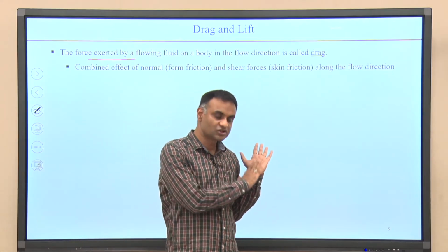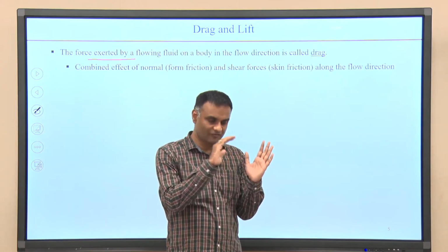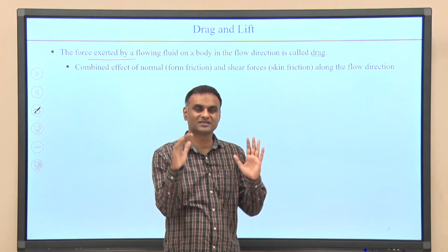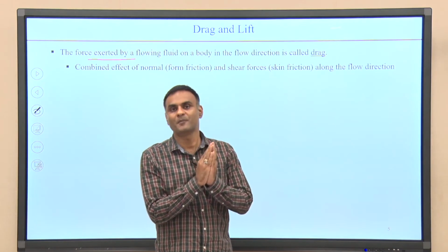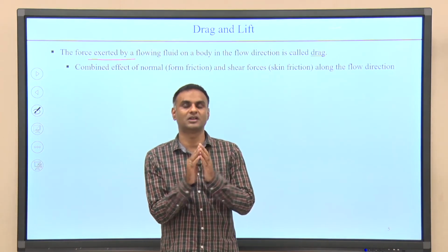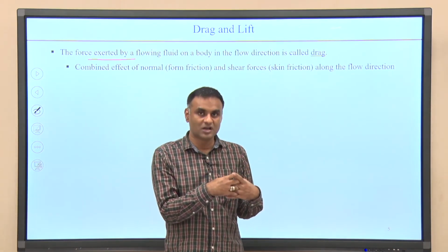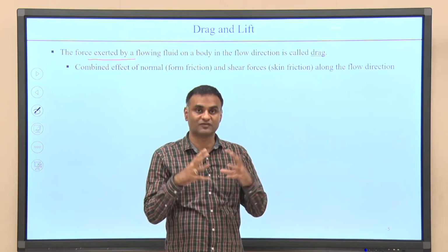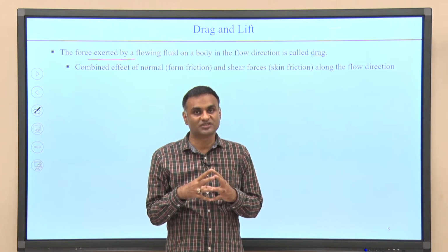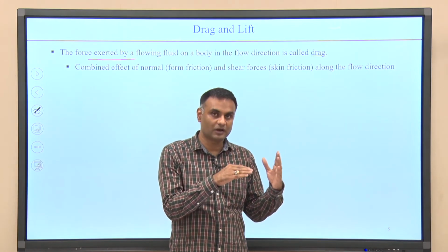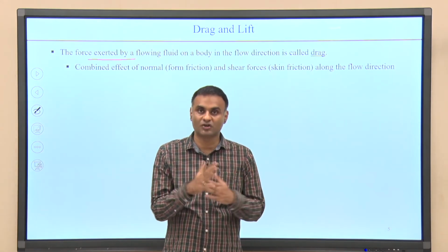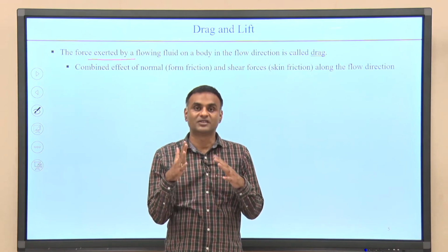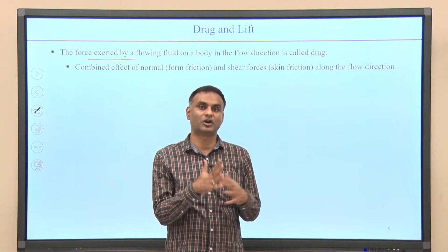Now, this drag can be because of surface forces. When a flow happens, the flow will come in contact with the surface of the body, and so there will be surface forces on the body because of the fluid, and these forces can be in the form of pressure forces or viscous forces. Viscous forces can also have normal components.